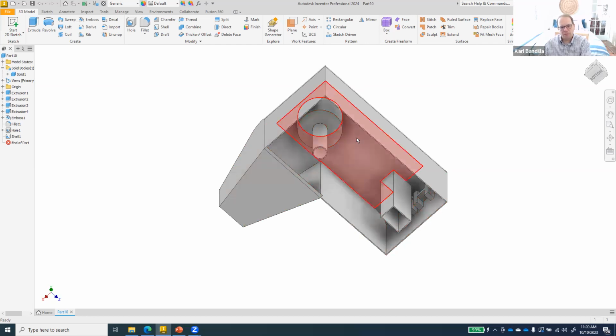So you can see it's all very well hollowed out. If you want to hollow something out and have a hole go through it, be careful that you do the holes later, because otherwise it's going to hollow around those holes as well. Right? So as you can see here, it leaves those out there. So that is the shell command.